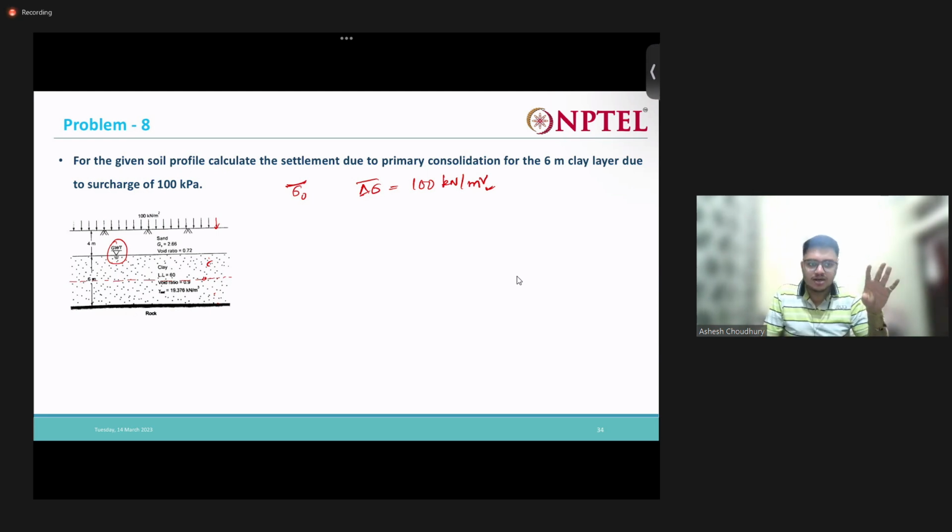If the tolerance is reached, that will be the optimum number of layers into which we should divide. But for our purpose, we just take the center of the clay layer and average it. No need to divide it into a number of layers. Let us divide it into two segments by taking it at the center. Let us find out.